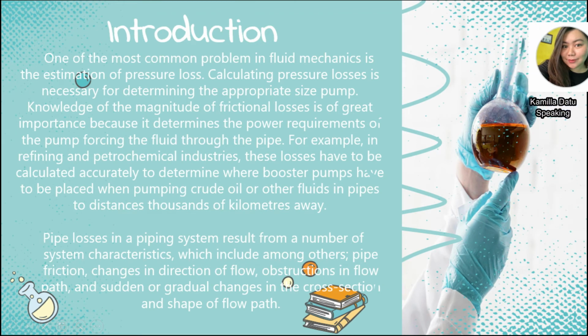Introduction. One of the most common problems in fluid mechanics is the estimation of pressure loss. Calculating pressure losses is necessary for determining the appropriate size of pump. Knowledge of the magnitude of frictional losses is of great importance because it determines the power requirements of the pump forcing the fluid through the pipe. For example, in refining and petrochemical industries, these losses have to be calculated accurately to determine where booster pumps have to be placed when pumping crude oil or other fluids in pipes to distances thousands of kilometers away.